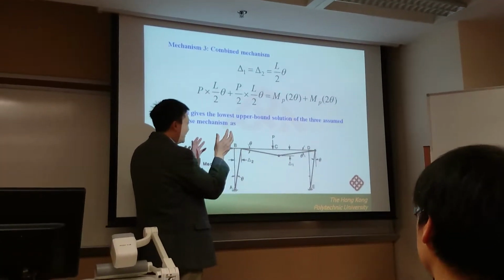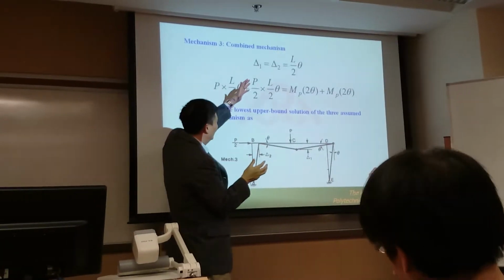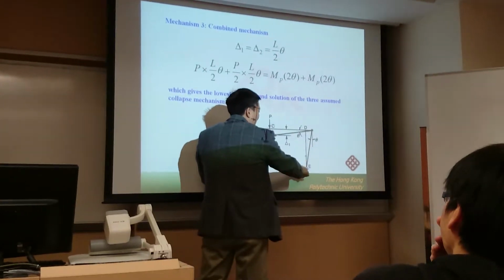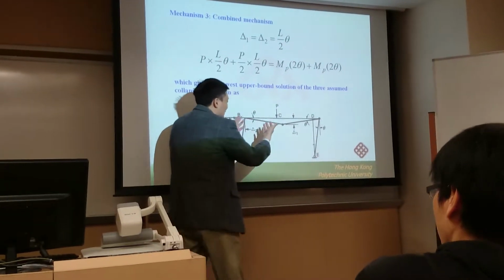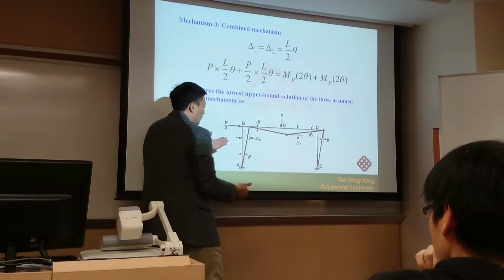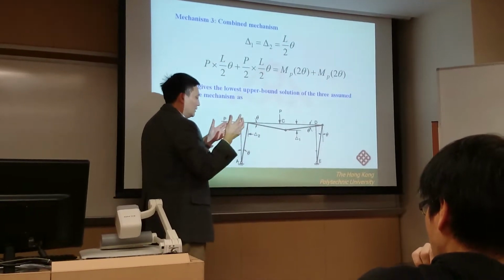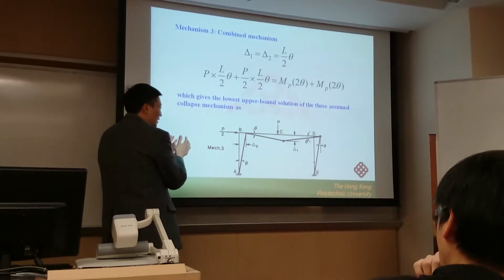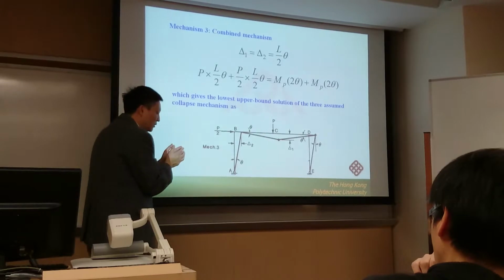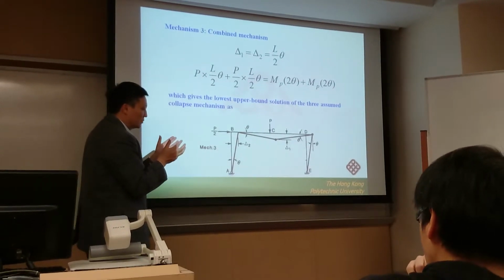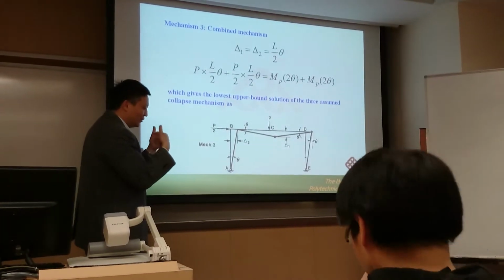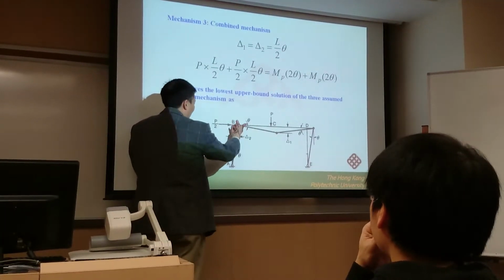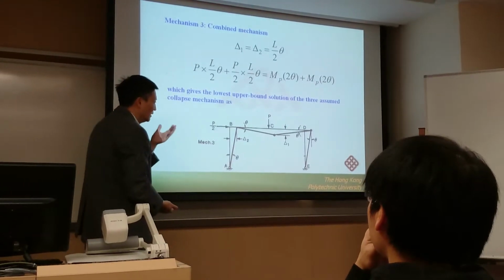But please understand, when we obtain the collapse force, we use a virtual displacement like this. This is also a virtual displacement. But when you do the moment check, in principle you have to introduce a different virtual displacement. How to introduce this different virtual displacement? You just need to introduce a virtual displacement to make the moment at this section available.